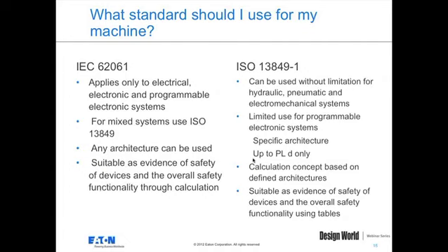So we've gotten down to type B, and now we have 2 standards. You have IEC 62061 and ISO 13849. These are both under the parent safety standard of IEC 61508, but they provide simplified and documented approaches to addressing functional safety on a machine. So from the beginning of addressing what level of safety you should design to, calculating all the different parameters of your application, and giving you an end result and comparing that to what level of safety you needed.